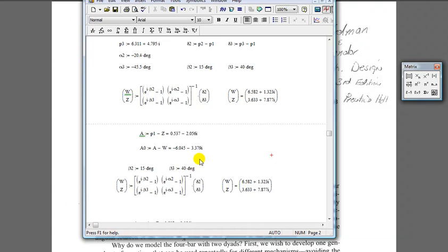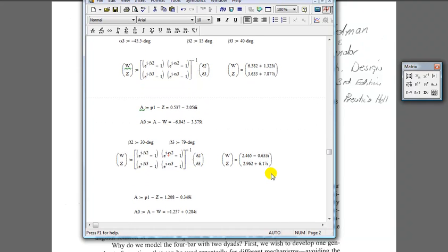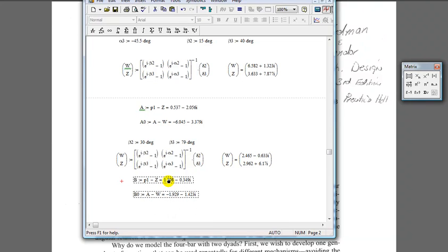Okay, and now if I just change my betas, maybe I'm going to let this one equal to 30 degrees and 79 degrees. Then I get new W's and Z's, and I get new coordinates, but maybe I would choose to call this one a B, and this grounded pin joint a B0. And now having an A0 and an A, and a B0 and a B, that totally defines a 4-bar mechanism. I have no idea if it's any good, but I've gotten one pair of solutions to get to one 4-bar.